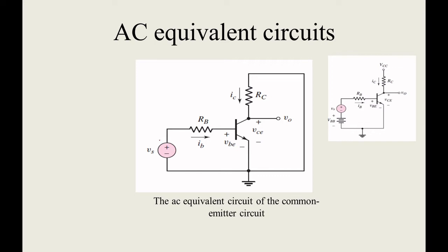So now comes a very important part, you can clearly observe here. This is the given circuit. I want to convert this given circuit into the AC equivalent. How? The first thing you want to do is consider your DC supply to be 0. I want to remove it, this is the first assumption. Second assumption, you can remove this part and this part, then the corresponding passive elements are connected to the ground, that's all. That's what they have done here.